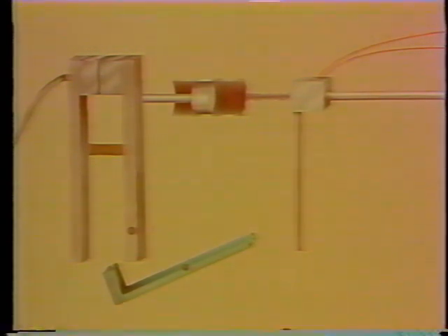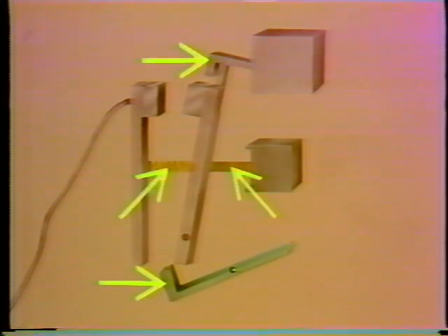When the contacts are closed, the solenoid also closes and the air pressure bleeds off. There's no longer any air pressure to push on the piston, so it stops moving. The latch then holds the contacts closed. This circuit breaker has two latches and two springs. Turning a switch at a remote location releases the latch that's holding the contacts open. When that latch is released, the spring pushes the contacts closed. The other latch then holds the contacts closed until the breaker is opened again.